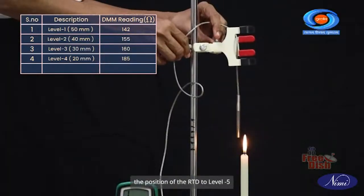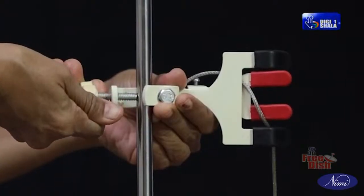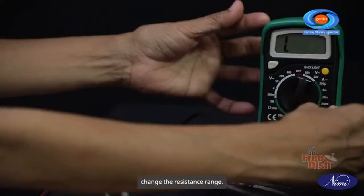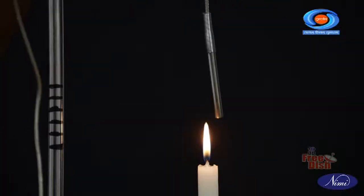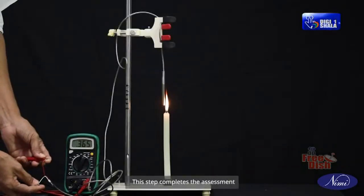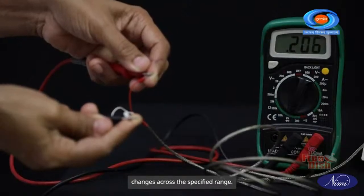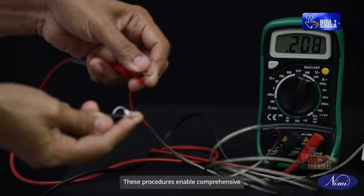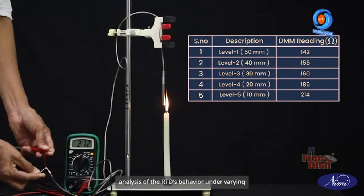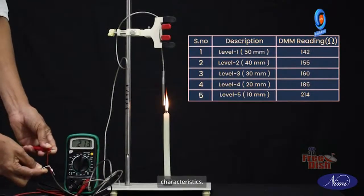Finally, change the position of the RTD to level 5, which is 10 mm. As temperature increases, the resistance changes. Note down the corresponding reading. This step completes the assessment of the sensor's response to temperature changes across the specified range. These procedures enable comprehensive analysis of the RTD's behavior under varying thermal conditions, facilitating a better understanding of its performance characteristics.